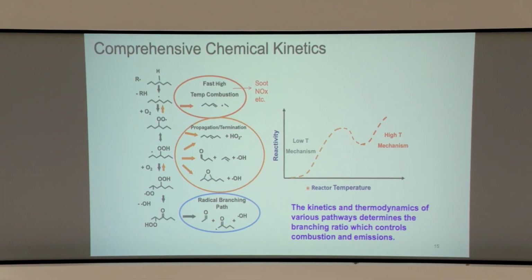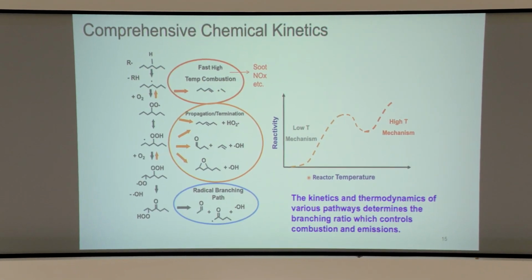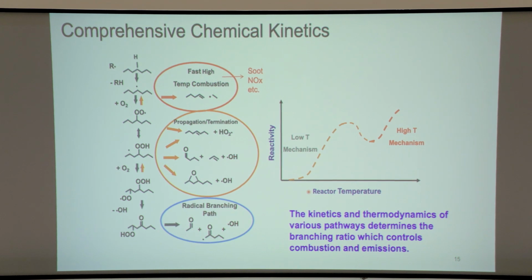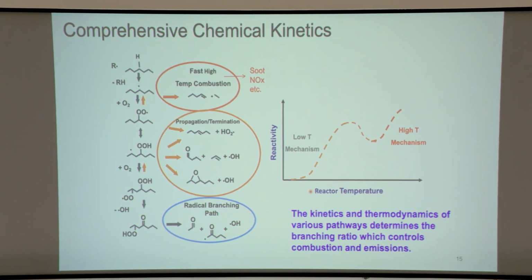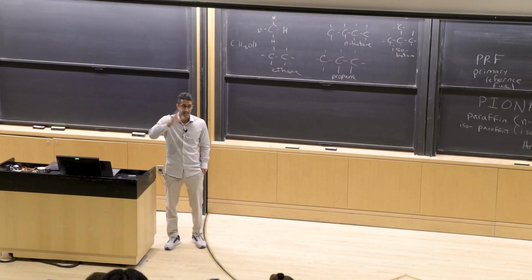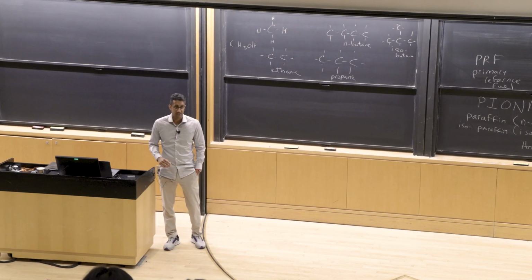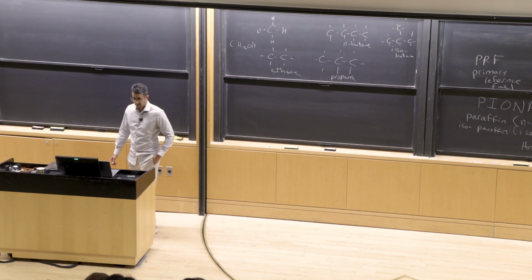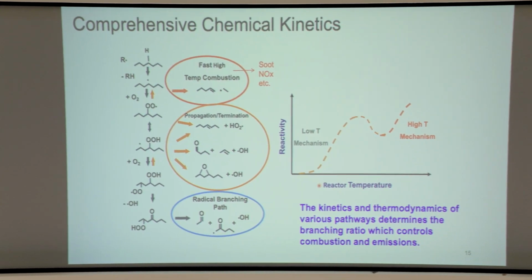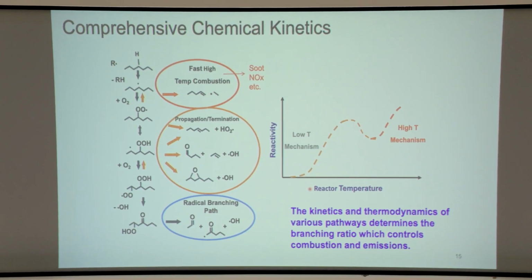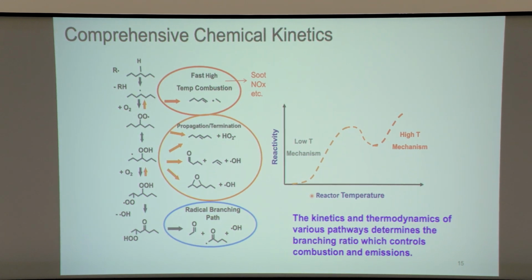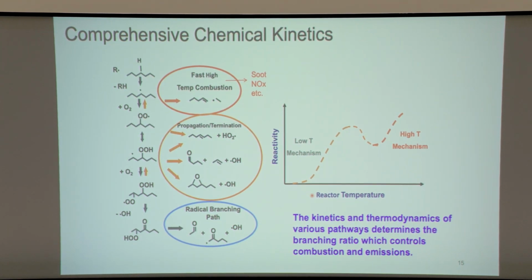Gas turbine, most of the time, high temperature. Why? Well, you typically have a ring combustor. These flames are all lit, mostly initially by the pilot, and then you have a continuous burning process. It's typically a high temperature combustion phenomenon. But as you go more lean premixed combustion, these low NOx combustors, people are starting to study how chemical reactions already start happening before the fuel enters into the combustion chamber.